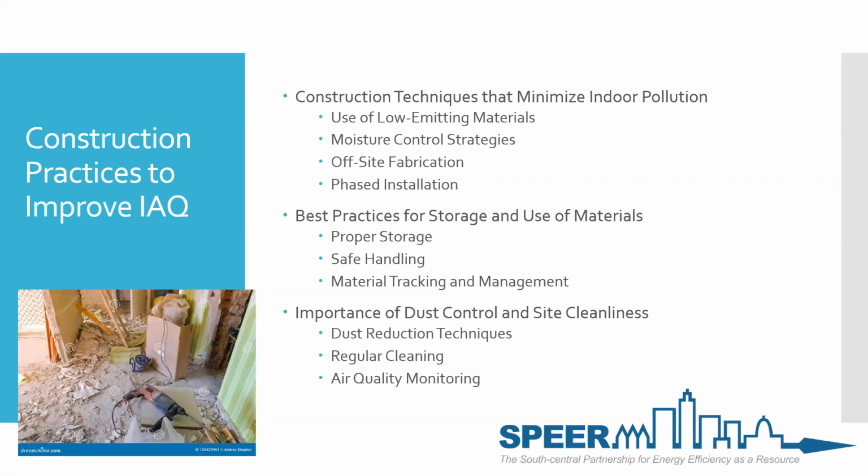Storing wood products off the ground. In LEED, that's a big thing. Wood products, even wood framing, can't just be in contact with the ground. It needs to be held up off the ground and/or covered so it's not degrading or has any degradation to the product itself.